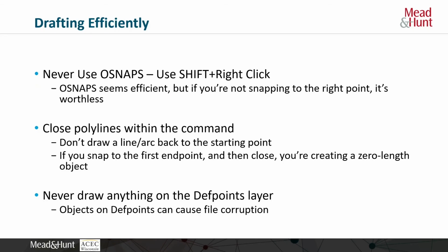Also, never draw anything on the def points layer. Objects on the def points layer can actually cause file corruption. Def points was a layer introduced, I believe, for the little pick points on like dimensions. And that is it. Don't add anything to that layer. I promise you, just stay away from it. Create your own no plot layer, or use a no plot layer that exists within your template. Don't draw anything on def points.